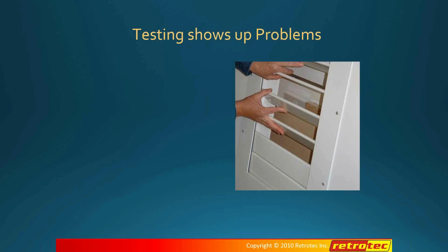So the free vent area that the manufacturer specifies might be the free vent area of the vent under ideal conditions if it fully opened, but we need to also measure the vent path, which includes all the ducting and the cat flaps or the ring louvers or anything all the way in the path. So that's why we came up with a procedure to actually measure the vents just to make sure that there won't be a problem.